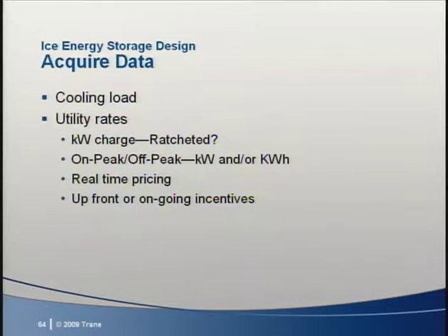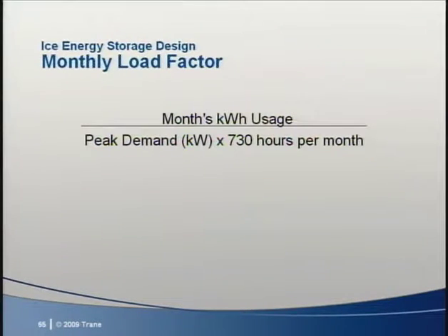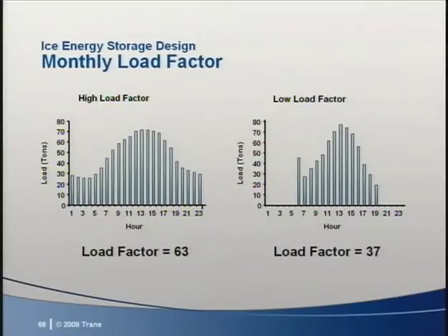The rates, in whatever shape they come, tend to reward consumers with higher load factors. For some rates, utilities even look at a building's monthly load factor to set its rate for the next year. A monthly load factor is defined as the month's actual kWh consumption divided by the peak demand times the number of hours in the month. Utilities design rates that reward high load factors, consumption that is more even 24 hours a day. They penalize low load factors, that is peaky consumption.